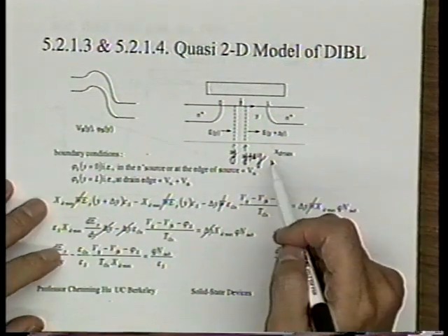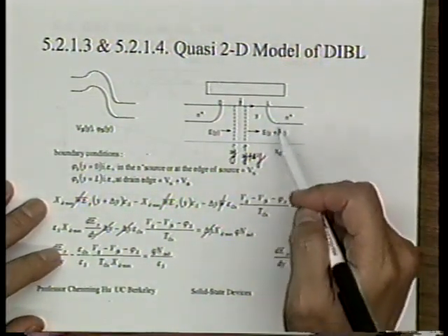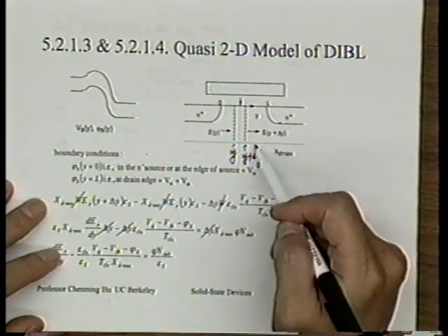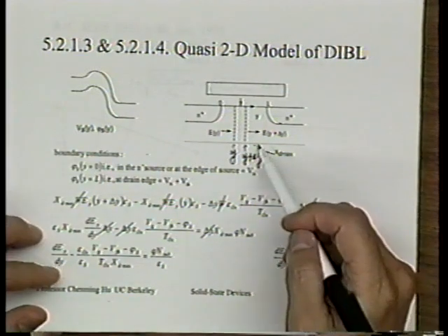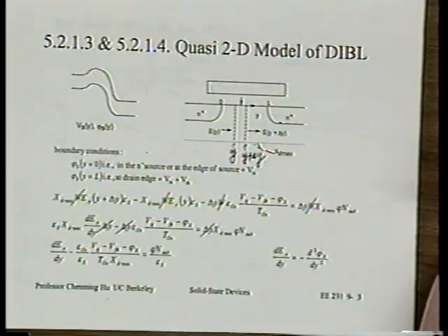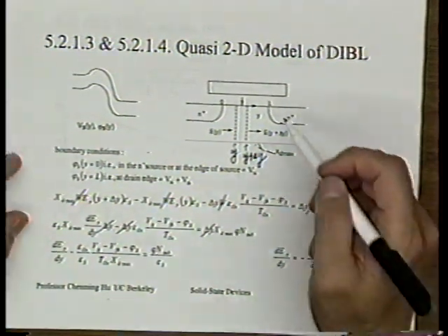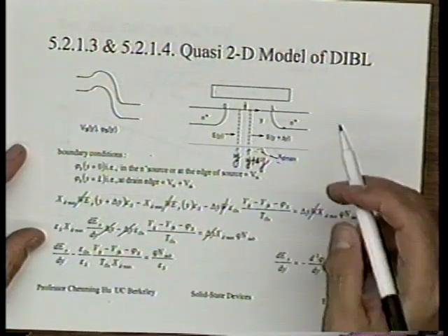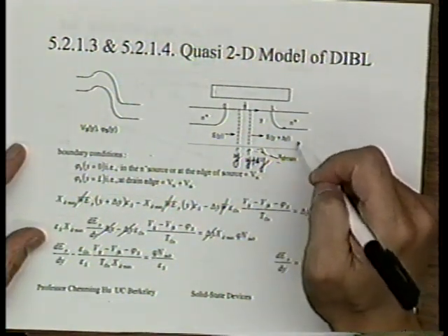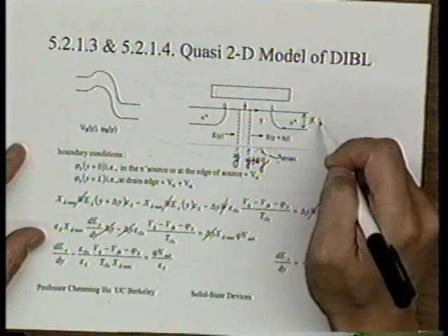One is that how do we know this X depletion is not going to be pushed down by the junction? This is what Jane was asking earlier. How do we bring the junction depth explicitly? We cannot. We just have to think qualitatively. Well, if we make the junction deeper, you're going to push this down also. We know that. We don't want to use it as X depletion plus Xj either. We don't want to do that either.